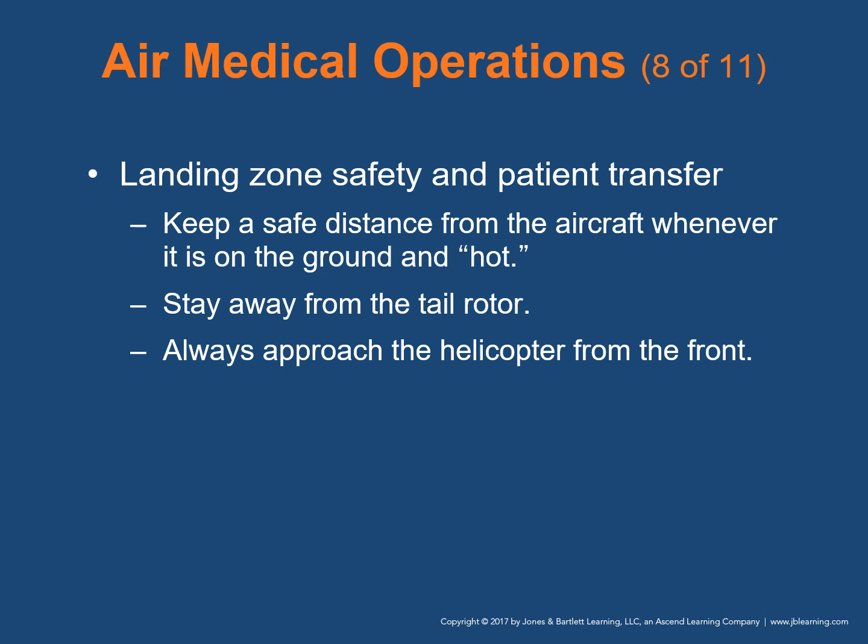Always approach the helicopter from the front, even if it's not running. When you approach the aircraft, walk in a crouched position because the top rotors actually hang downwards. You can't see it, especially when they're moving quickly, but they hang downwards. So you need to make sure you're crouched so that the tips of the rotor blades don't get you.